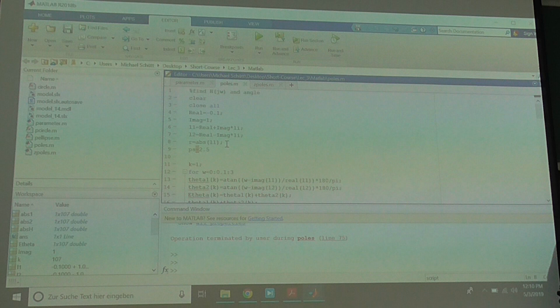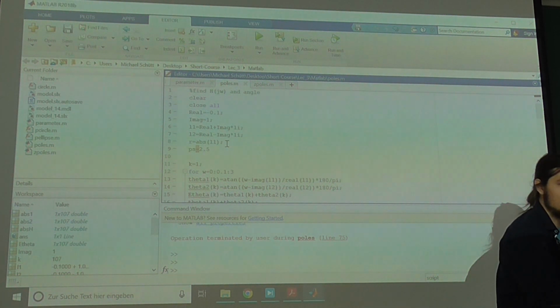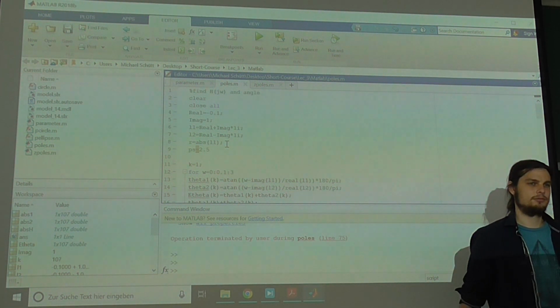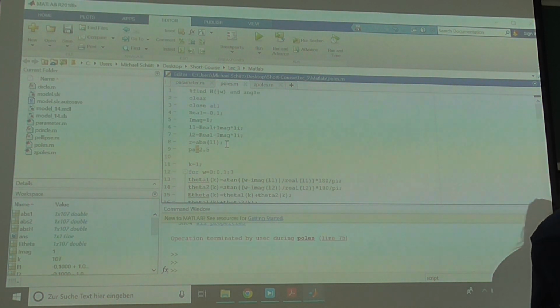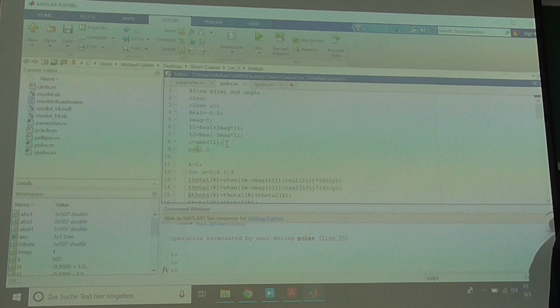Why VDC squared? That's based on the power relations. Yeah. So 1/2 C VDC squared is the energy, and the rate of change of energy would be the power to the capacitor. And then we have the input-output relationship between the powers. So very good. Actually, yeah, the energy on the capacitor is VDC squared times C over 2, right? So VDC squared is really the information of the energy.